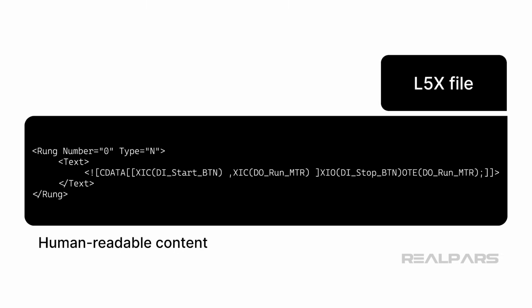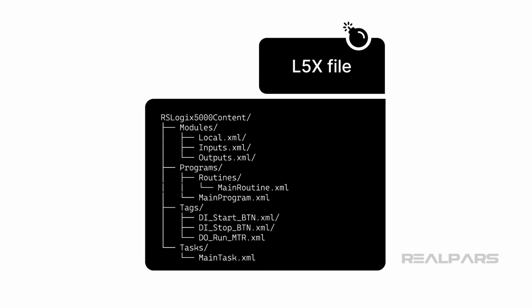The problem with working with L5X files is that they can be very large files, and the content within the file can move around. To work around this issue, the VCS Custom Tools explode an L5X file into components. This explosion lets you work with smaller, well-organized files instead of one massive one, making it easier to see what has been modified at a glance.